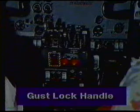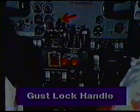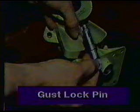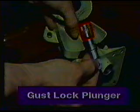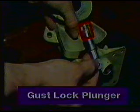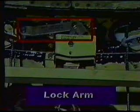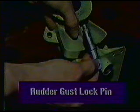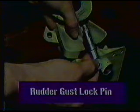Components of the gust lock system include the handle installed in the pedestal, which is the gust lock handle, or gust lock control. The unit that actually locks each control is called the gust lock pin. The spring-loaded portion of each pin is called the gust lock plunger. The unit that connects the gust lock pin and gust lock cable is called the lock arm. The component name usually includes the name of the surface controlled, such as rudder gust lock pin or aileron gust lock arm.